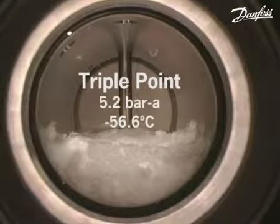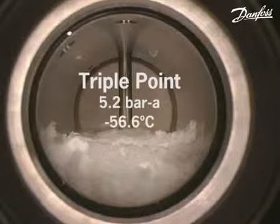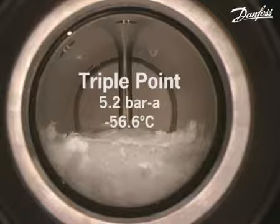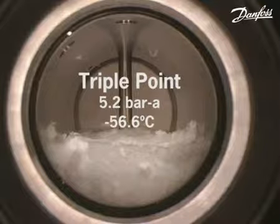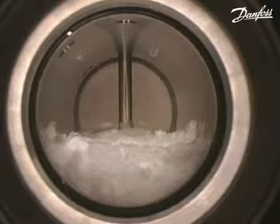Solid CO2 begins to form once a pressure of 5.2 bar absolute and a temperature of minus 56.6 degrees C has been reached. The triple point is the only pressure and temperature combination at which solid, liquid and vapor CO2 can exist simultaneously in equilibrium. As the pressure continues to fall below the triple point, only solid and vapor are present in the cell.